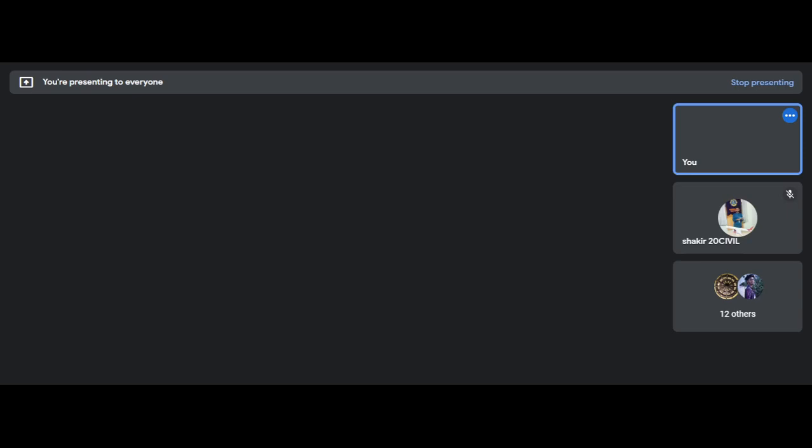So we'll see the next question, question number 8. Which of the following are the removal mechanisms of leachate from landfill? We have first option, drain by gravity, second option, blowing, third option, pumping, and fourth option, siphoning. Leachate removal is done mainly by two techniques. The first technique is drain by gravity.